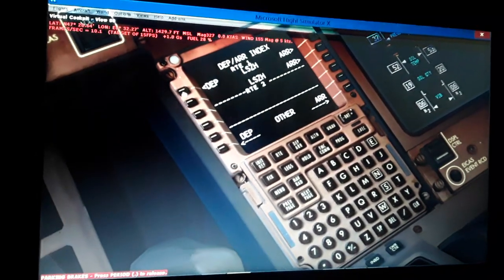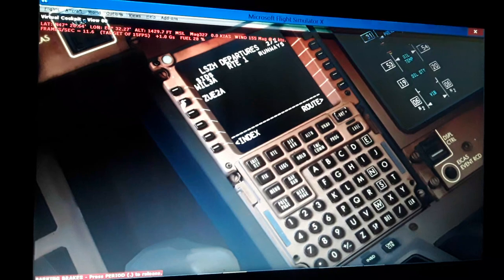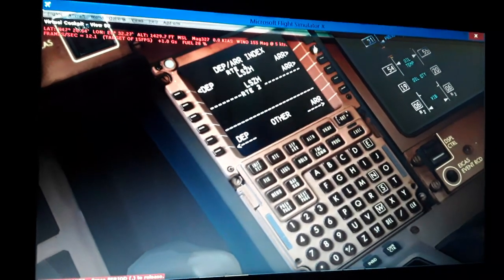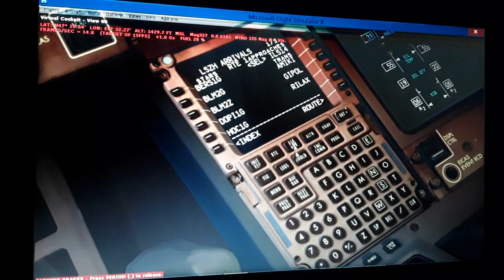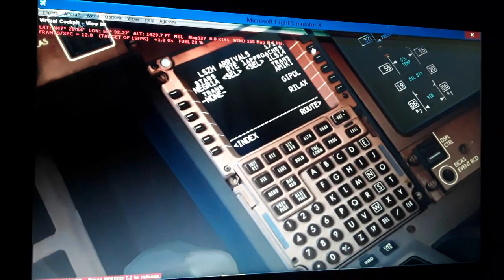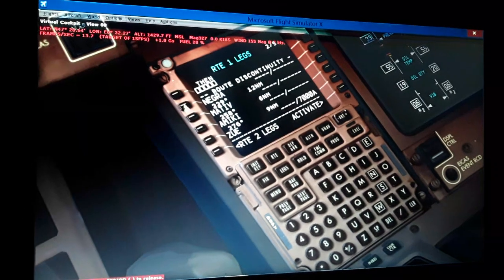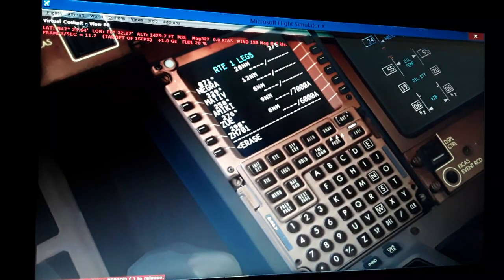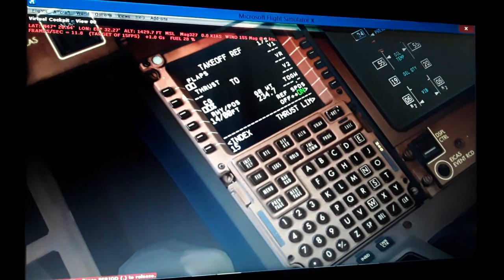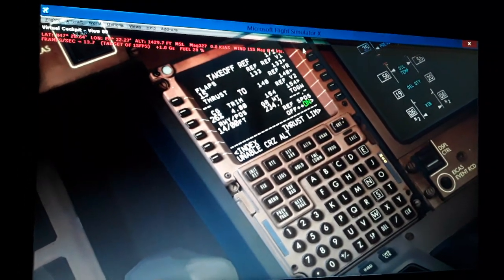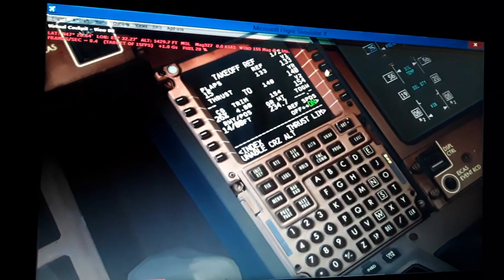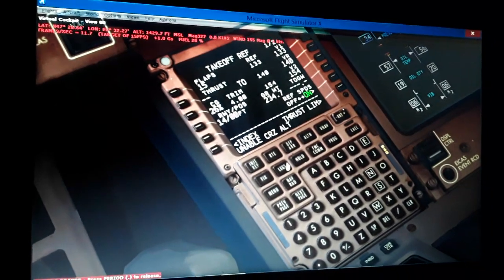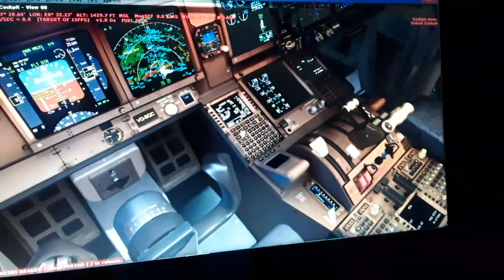departure and destination. You copy paste departure, destination, airport runway 14, departure and arrival. So we're gonna select this departure. You're gonna see in the legs, and this arrival. Iris 14, transmit, you're gonna have the legs here, cancel the discontinuity, activate and execute. And we're gonna have the flaps position, center of gravity, and the takeoff speeds for this takeoff weight and this runway. V1 will rotate in V2, so we have all the legs ready, so we are ready for takeoff.